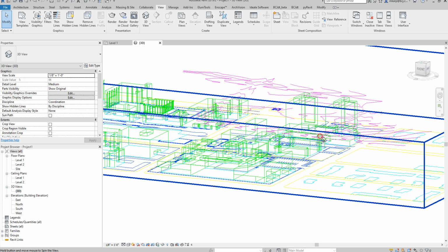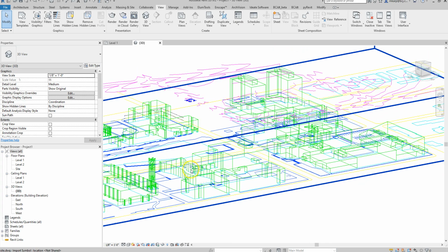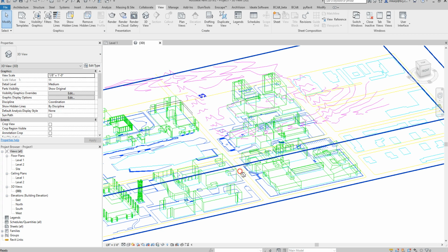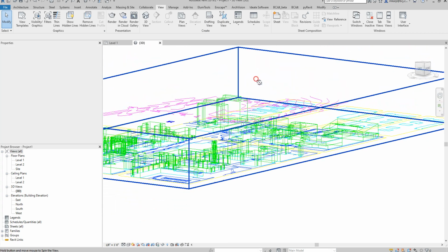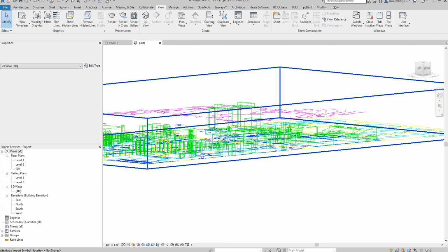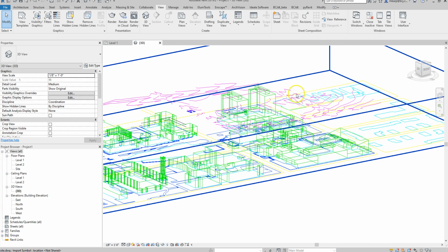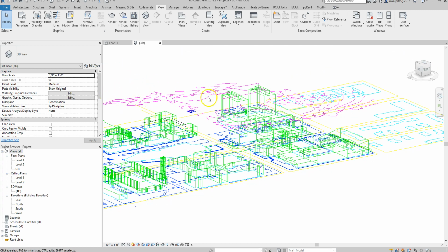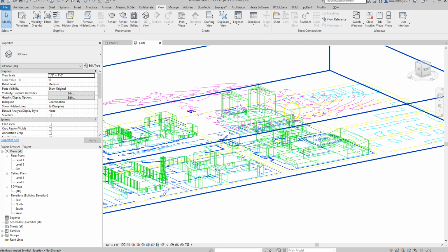So you can see there's actually 3D information for some of these buildings from the site, but then all of the CAD information is at 0, 0, and the site information slopes as does the actual site. So you're sloping from about 100 down to 83 or so in 1 foot increments.